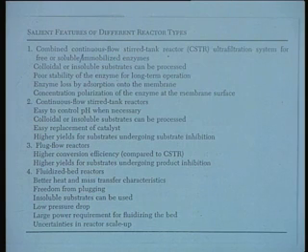And if you handle, particularly in the case of even a CSTR, many enzymes or carrier particles that are shear sensitive or can undergo a lot of attrition during use, the CSTR becomes a disadvantageous system, because if the carrier particles get disintegrated during use, it will involve loss of enzyme.